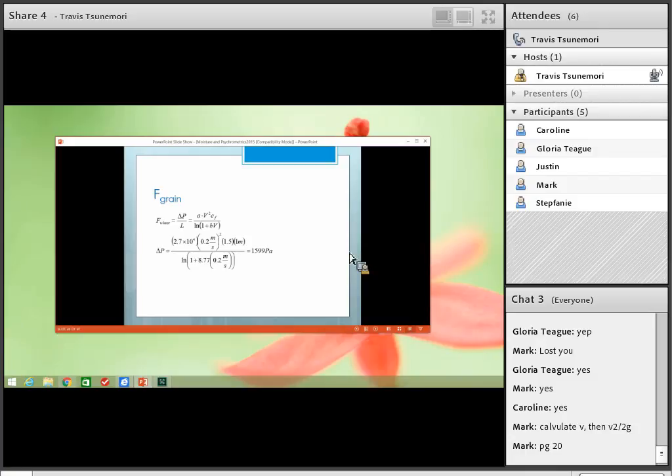And then we have our velocity through the bin, because we're doing the friction loss through the grain, is 0.2 meters per second. You're going to square that. And we had our correction factor as before, which was 1.5. And now we've got 1 meter multiplied there because what we've done is multiplied through by L, because really 1 is delta P. So I just multiplied L to the other side, and that's what the 1 meter is.